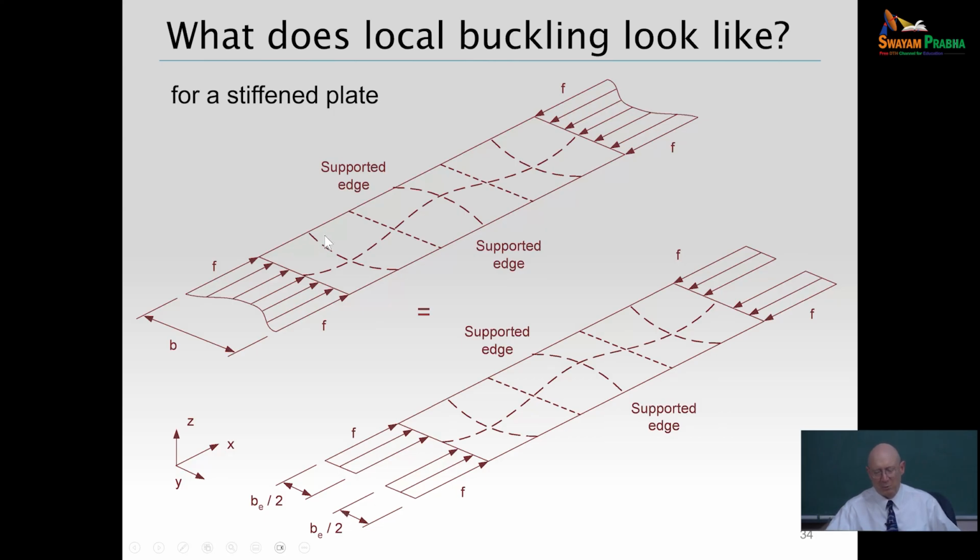Again, if you take little f and say, okay, if it's just a plate, if it's not in a column, take f equals fy. So my strength of the plate would be when I develop fy at the edges, but I'm going to lose some effectiveness of the plate for its strength out in the middle, right? So that's basically what plate local buckling looks like. That's how we're quantifying things with effective widths.